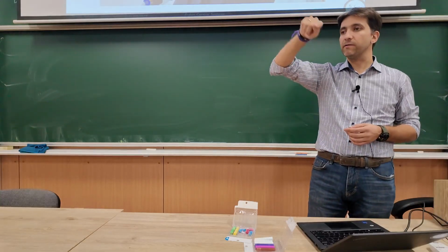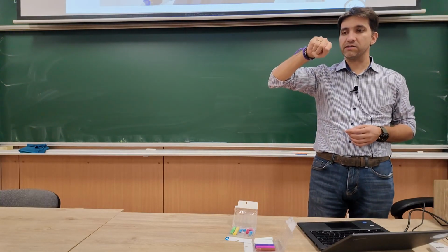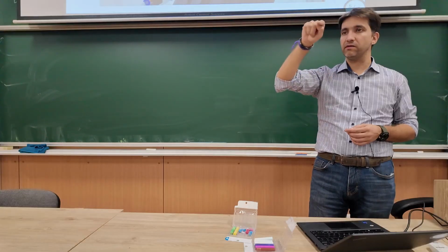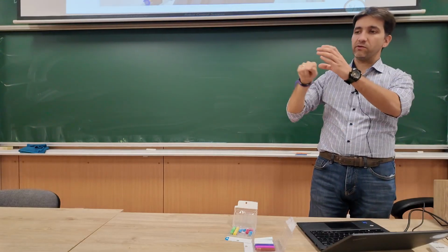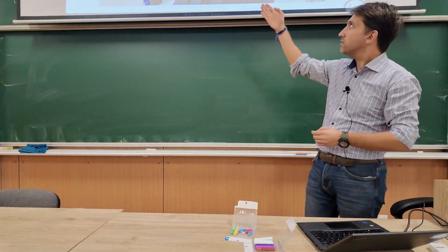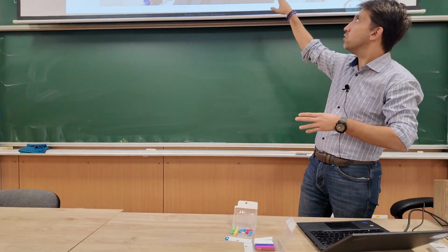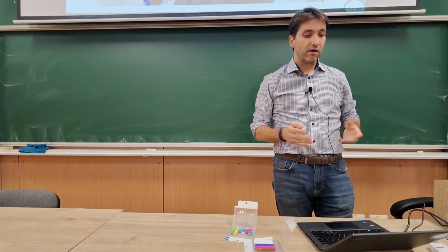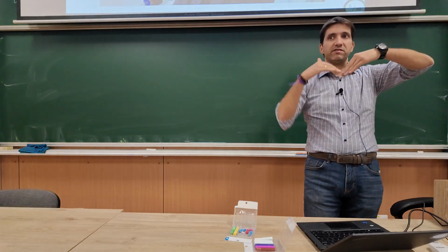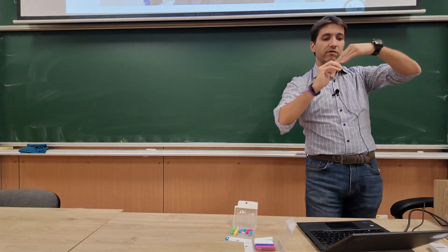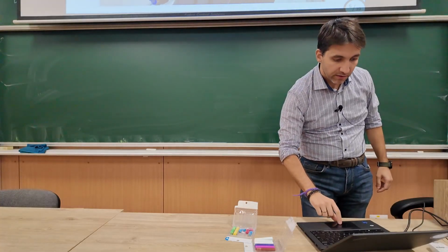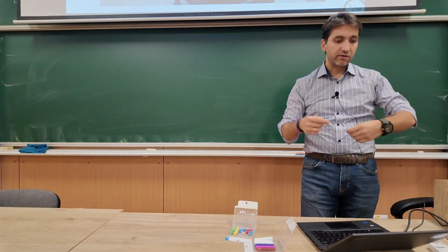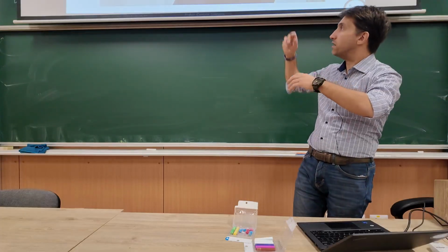For the drilling, we had to have a certain orientation where we kept the drill perpendicular to the surface. Let's say here, if this is gluing or welding or whatever it is, again we have to be perpendicular to the two surfaces, or have a certain orientation around this surface so that we can perform the task properly.